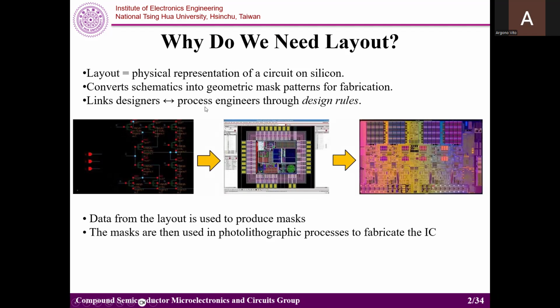First, I will explain why we need to draw the layout. Layout is basically a physical representation of a circuit on silicon. It converts your schematic into geometric mask patterns for fabrication. So it links the circuit designer and the process engineer, helping them communicate through design rules to make sure that your circuit can work normally after the fabrication process.